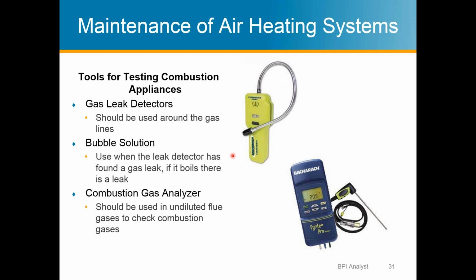When you do find a gas leak with a gas leak detector, you would want to use some bubble solution. What that does is help verify that there is a leak, because these leak detectors are very sensitive and will pick up the smallest, tiniest gas leaks. Many times I'll call a gas service representative out and I know there's a leak there and they won't fix it because it's too small for them to fix.